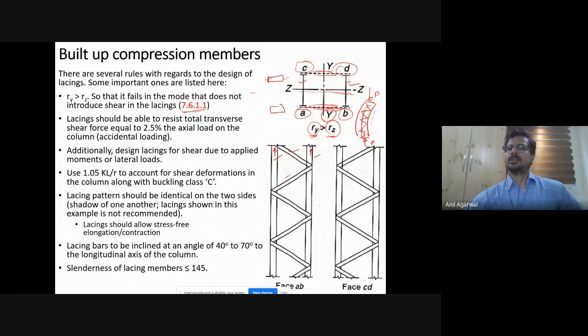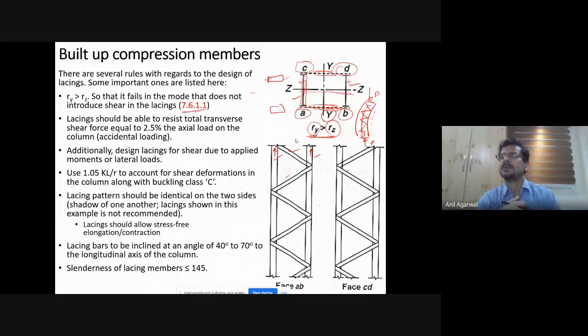Okay, and all the shear force will be transferred through this web, which anyway was designed to carry a lot of shear force because this was a hot rolled section. So they have a lot of shear strength. Then there won't be any issue. That's why this insistence on Ry being greater than Rc. Okay, I think I explained it in quite a bit of detail.